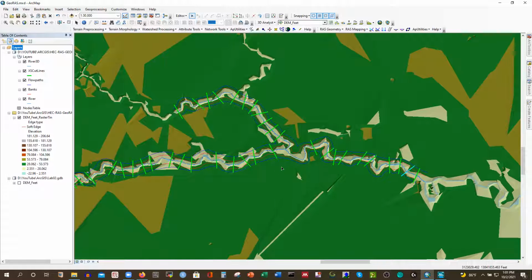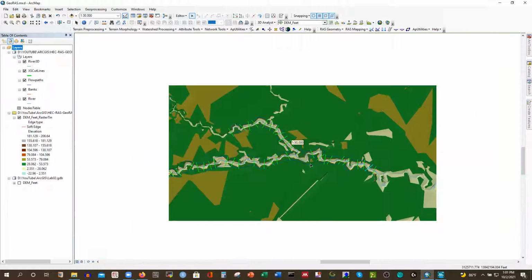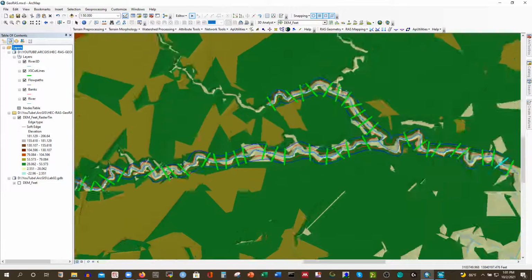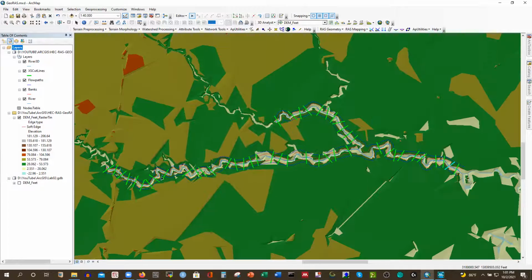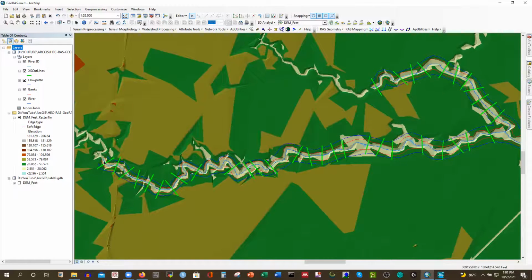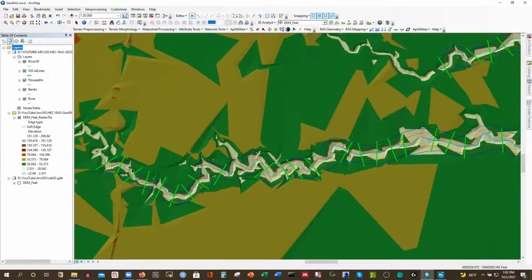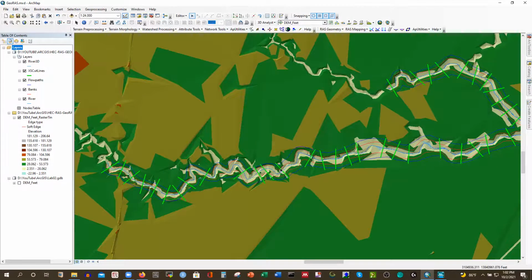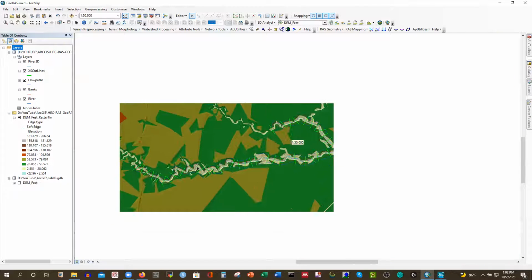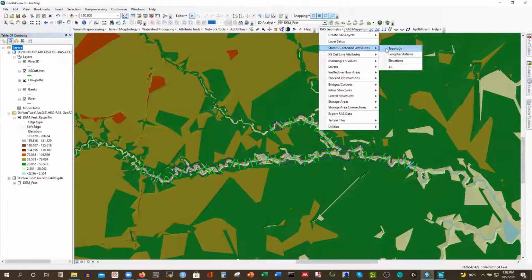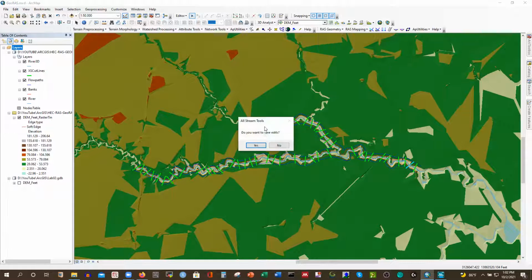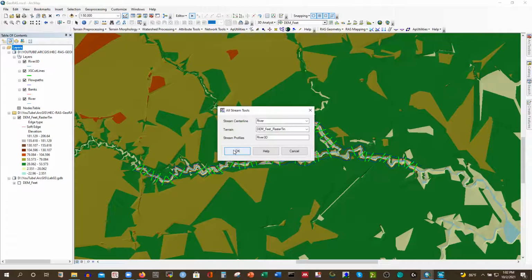I'm not going to do that right now, and you can even insert other stations, and I'm not sure if it's going to work or not, right? So these are the problems we have to deal with. You have to follow the rule that two cross sections are not allowed to cross or touch, but each has to cross the flow path, and then you'll be done. So we have to do the processing one more time. Here topology and everything, and then again it is going to do the same thing.